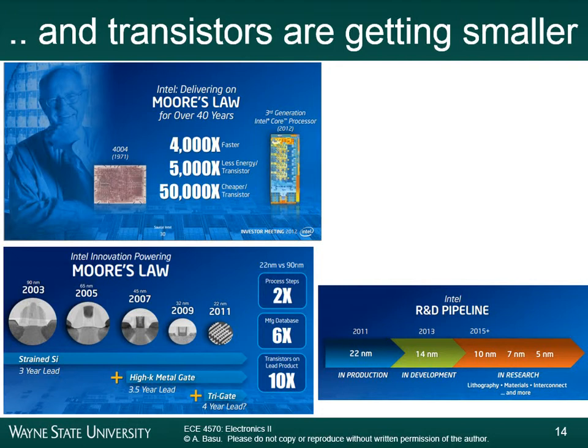However, over time, maintaining the performance of the transistor, I'm talking about the on versus off current, the power consumption, the ability of the transistor to behave as an ideal current source in analog circuits, the early voltage of the transistor, the threshold voltage, maintaining those parameters as you scale the size down, actually becomes tricky.